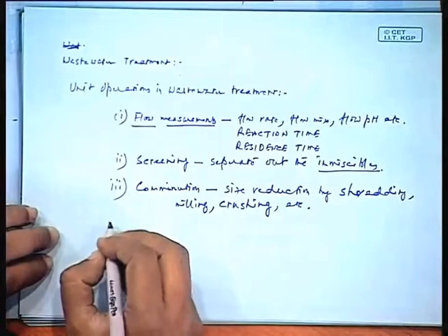One great and important part of comminution is that as soon as you break something, the surface area increases. The surface area has a great role to play: it increases the rate of reaction and exposes more area available for reactions. So comminution essentially does that. For example, if you take something like a leather bag in water and shred it completely into pieces, the biodegradation time of the shredded parts would be less than that of the larger one. As simple as that, because of the larger surface area of exposure. So comminution is a very important part.